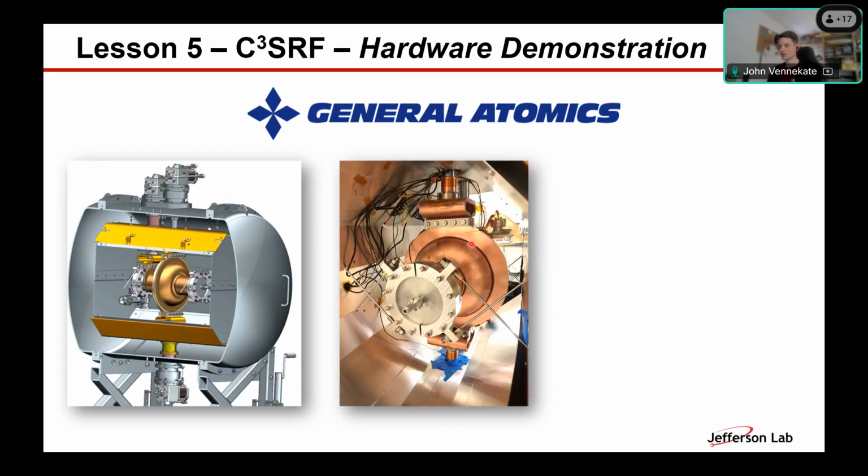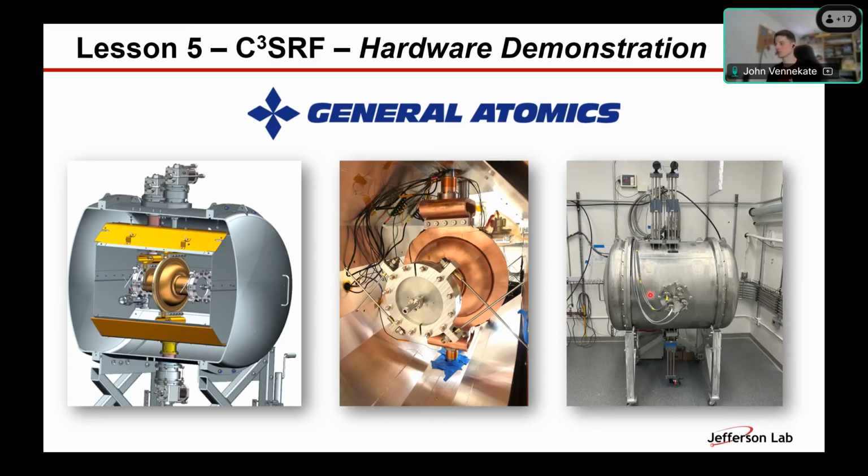And you have the bulk solid copper around the cavity itself that connects this cavity to this cryocooler. And with that, Gigi was able to operate this cryomodule, there's another picture of the facility over at GA, and demonstrate as a first proof of principle that we can have SRF technology delivering the same accelerating gradients for the electrons without any helium. So that was also a first of its kind demonstration of a single cell cavity with a highly usable gradient for the actual industrial application.